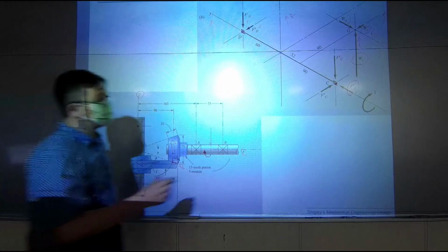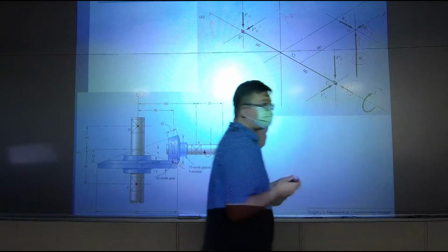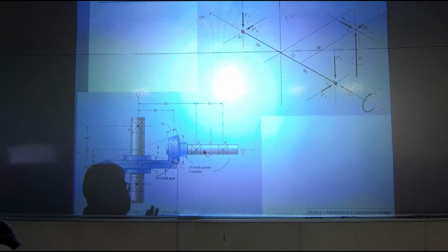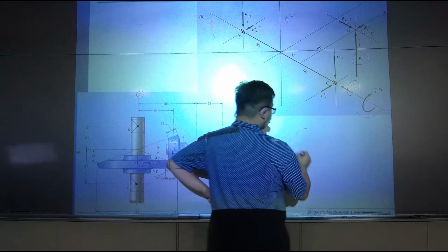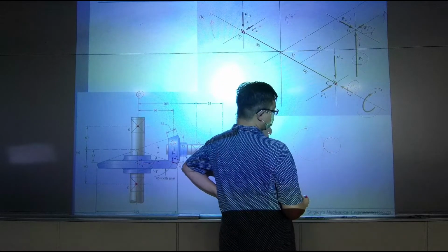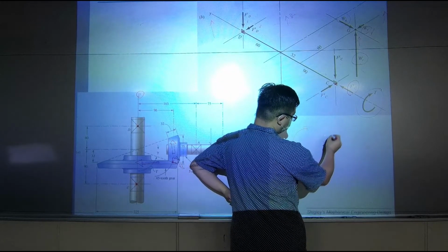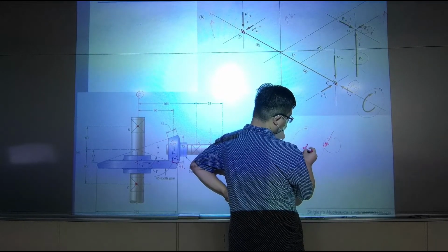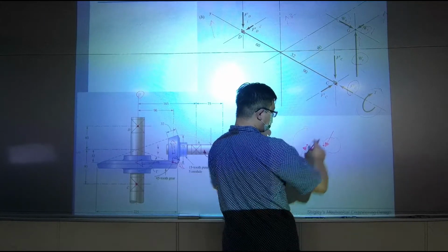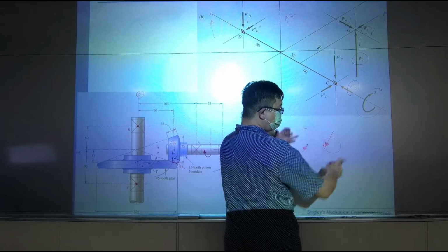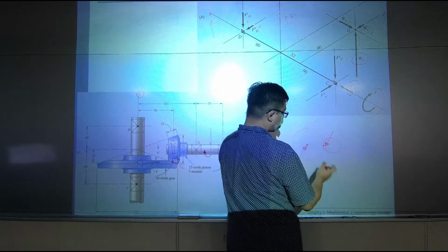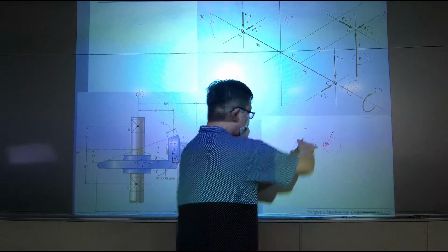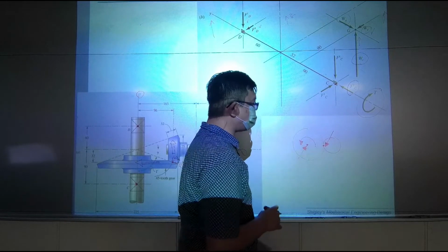And also, there will be reacting torque. How come there's reacting torque? Let's think about the bevel gears. When we have bevel gears, and if the external force comes this way, and the reaction force comes this way, then we are sure the force couple will rotate clockwise, and there should be a torque rotating counterclockwise to balance the force couple, the moment generated by the couple.